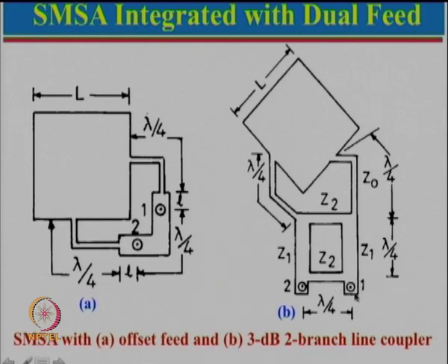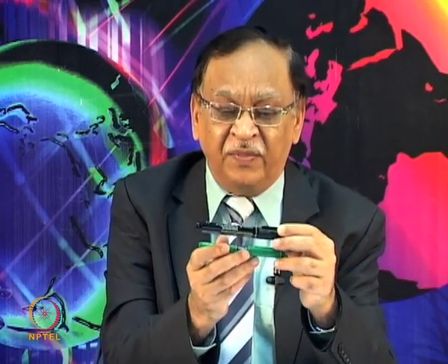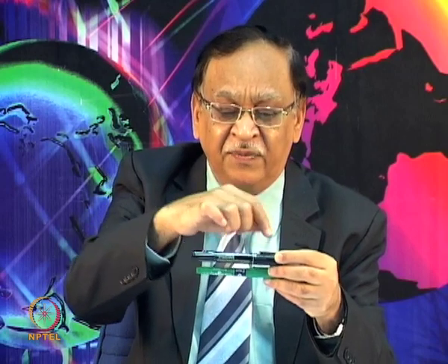For that we have to first understand the microstrip line. So, think about there being one microstrip line here. If I feed at this particular point, power will go to this end here, which is straightforward. Now, if I put another microstrip line in parallel with this line with a small gap, what will happen? The microstrip line will have some fringing field, and that fringing field will get coupled to the other microstrip line. So, some field will get induced into it.